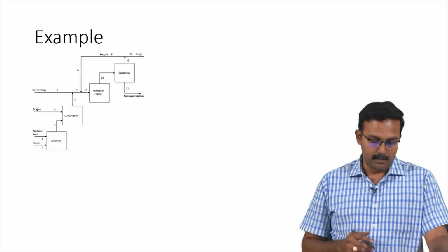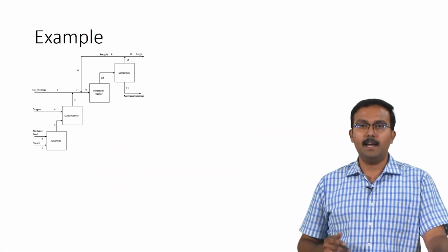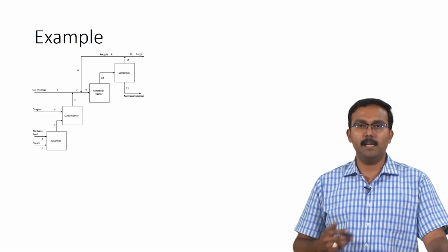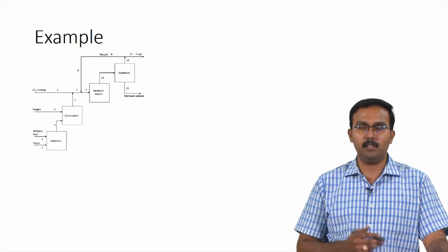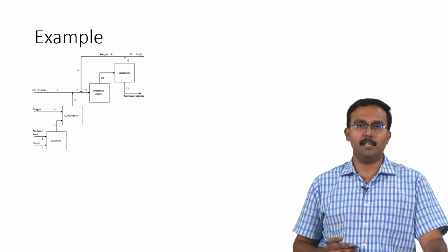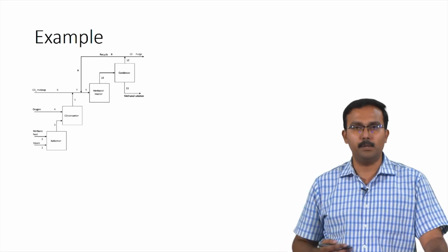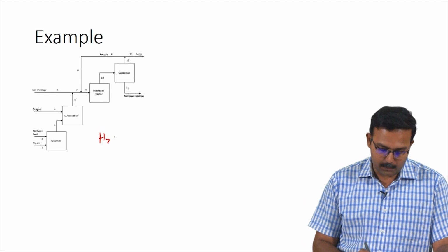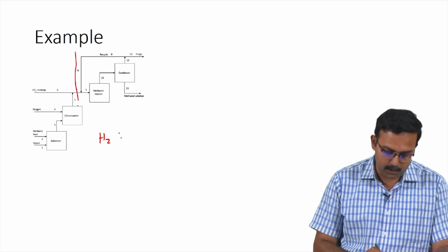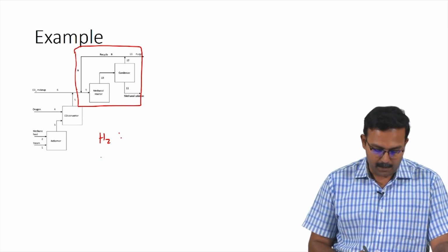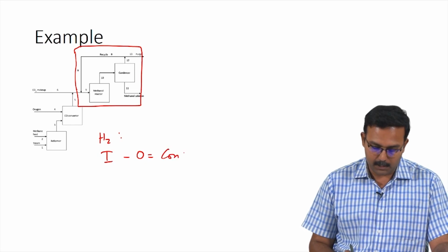For the system chosen, we have a methanol reactor where hydrogen is being consumed. We can calculate hydrogen consumption based on the information we have about the input and output terms for hydrogen. Using this, we will be able to calculate how much methanol has been produced. Let us try and do this. So, if we were to write the balance equation for hydrogen for the system chosen, what you would have is input minus output is equal to consumption.